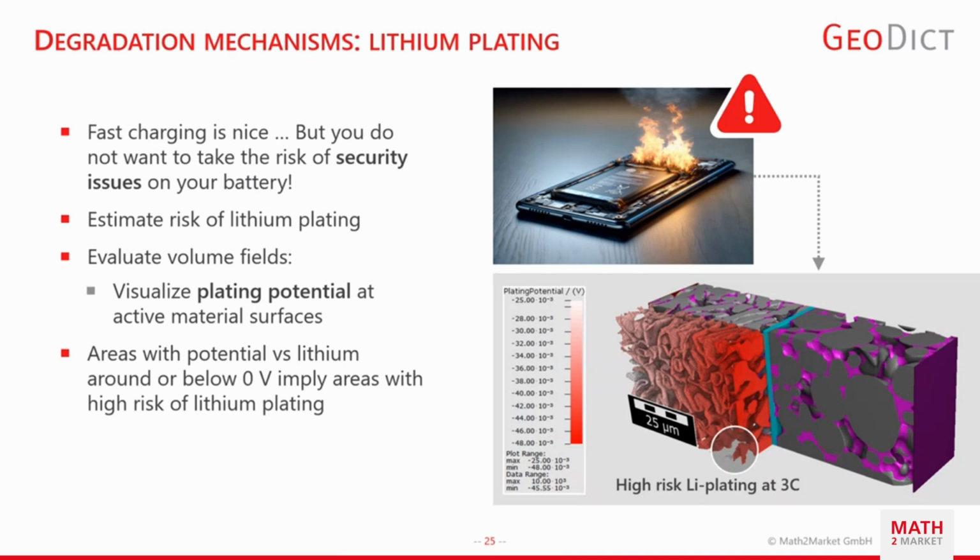So it's good for you if you know, can I estimate the risk of the lithium plating at certain conditions? And here you see a very fast charging simulation. So it was 3C charging rate. This means in only 20 minutes you fill the complete battery from empty to full.